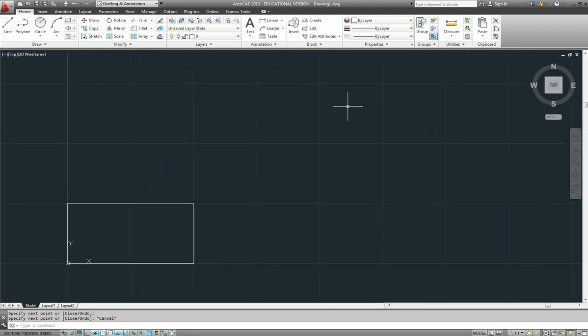You might be drawing that same box right out in space here. So let's say we were starting anywhere and we wanted to go 100 across to the right. Now there's a bit of a trap here, because with recent versions of AutoCAD there is a thing down on the status bar, an option called dynamic input. If that is on, the absolute coordinates won't work. So for the way we're drawing at the moment, just make sure that one is turned off. That's the dynamic input.